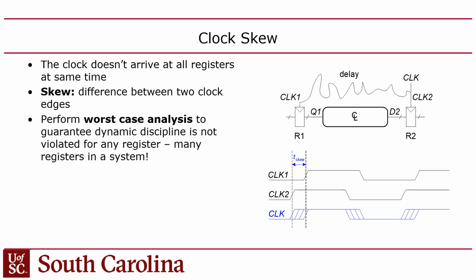Because the electrical signal is only moving as fast as you can charge and discharge capacitors. It's not moving at the speed of light like a lot of people think it does. It doesn't. Much slower than that. And because it's charging and discharging through resistors, there's resistance. So you can charge and discharge really fast, except that the resistor limits how fast you can. The more charge you have to charge or discharge, and the more resistance that's resisting the charging and the discharging, the more it increases the time, right?